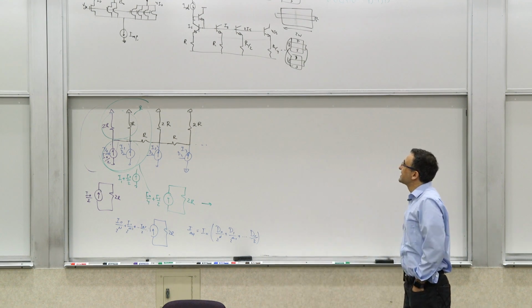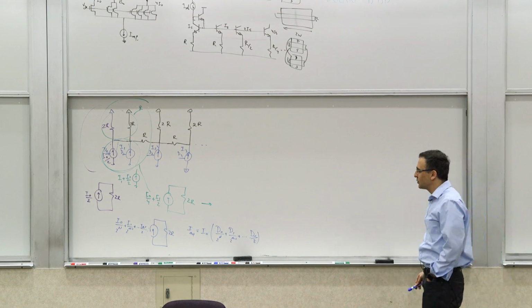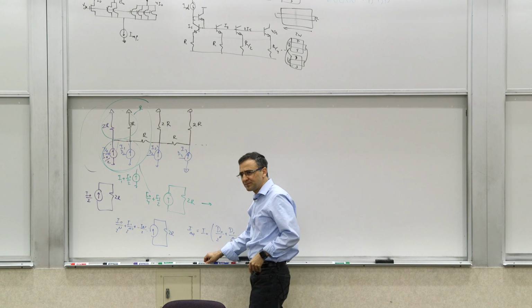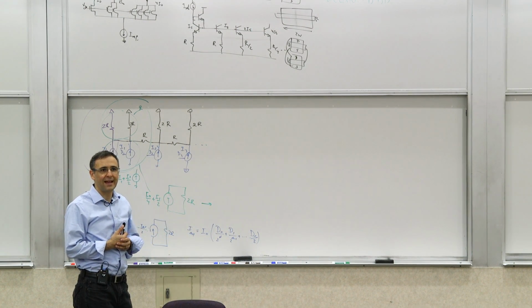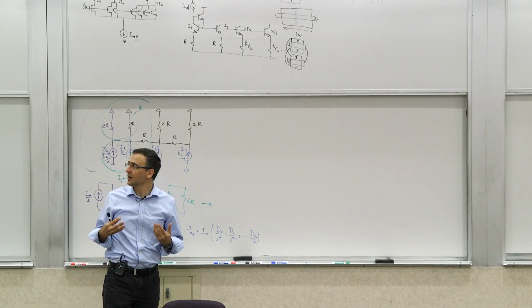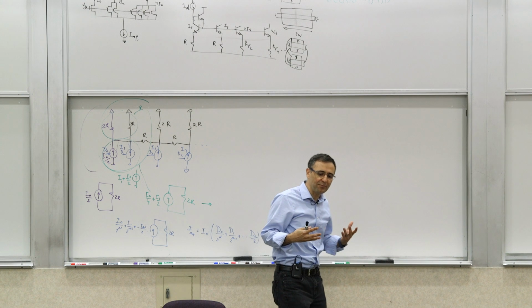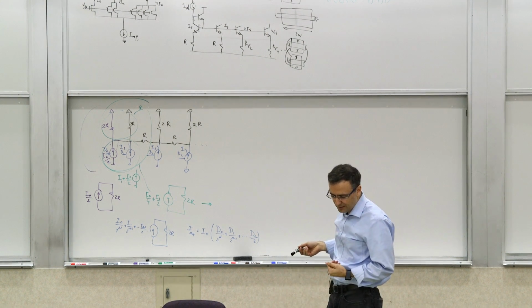So these were kind of current source based and resistive based. Are these the only ways of doing D2A? No, there are other ways. How about using capacitors instead of resistors and getting your divisions based on capacitors? Because capacitors do charge sharing, right? When you do charge sharing, you can take a certain amount of charge and share it differently between different components.